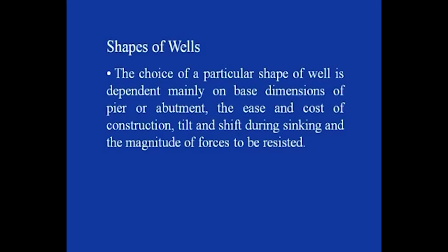Other factors which affect the choice are the ease and cost of construction, the tilt and shift during sinking, and the magnitude of forces to be resisted for any particular well foundation. We need to take all these things into consideration and then choose the appropriate shape of the well.